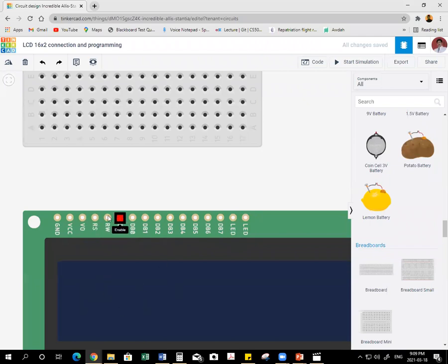The remaining 3 pins are register select, which we give to the power supply, read/write, which we give to ground, and enable. Enable means we enable the LCD to write something or not. If it is 1, the data pins get the input to the LCD and it will print it. If enable is 0, it will not display anything. So that's it. Very simple explanation. Don't worry, it is a 16-pin display. How to remember? It's very easy, it's not a big deal.